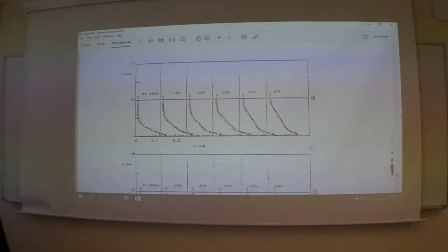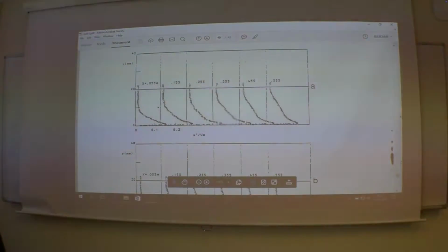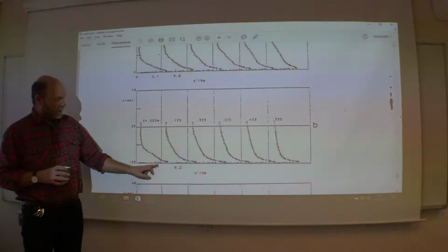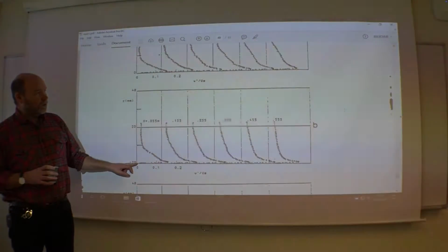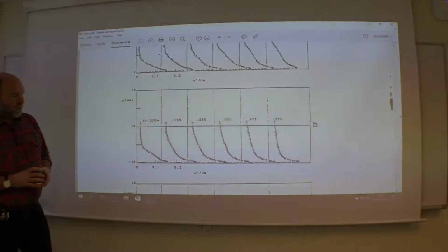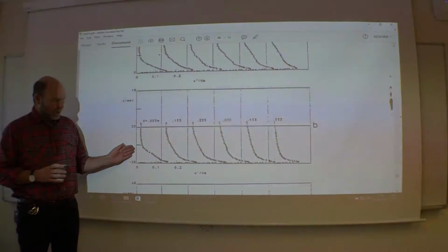For the turbulent intensities, that is the fluctuation squared. In a turbulent flow, they peak normally very close to a wall, very close indeed, and then go to zero on the wall itself. So here you are on the turbulent side, the unstable side.